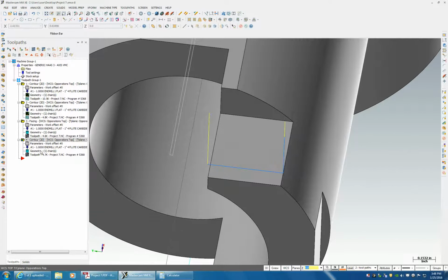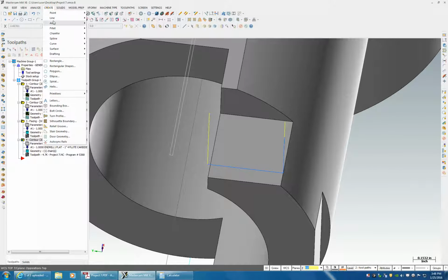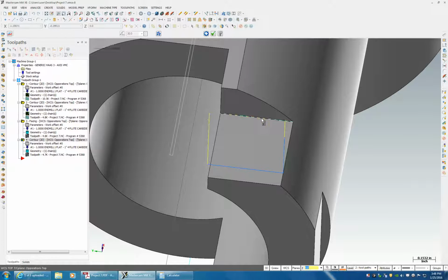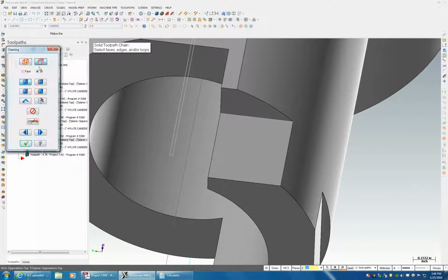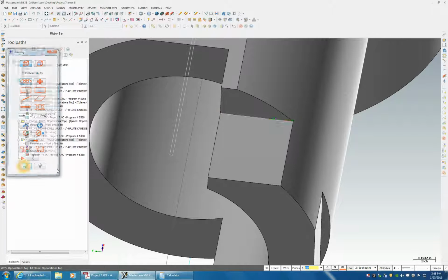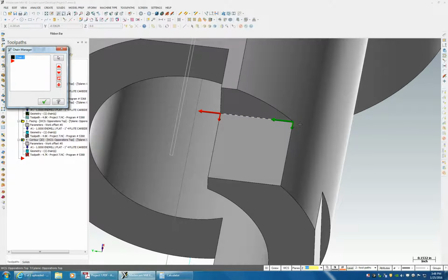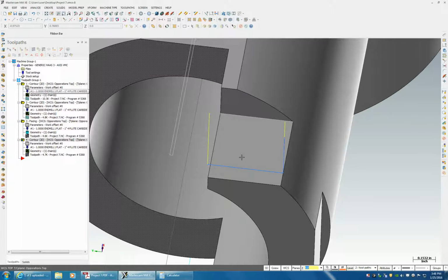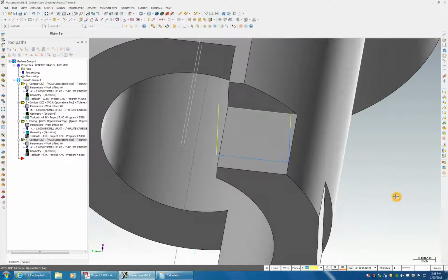Okay. So what I'm going to do this time is I'm going to create a curve on one edge. I'm going to rechain it using a wire rather than the solid face. So come to geometry, rechain all, switch over to wire. I'm going to select that chain. It's going in the right direction, compensation on the right side. Regenerate. Man, still doing it.